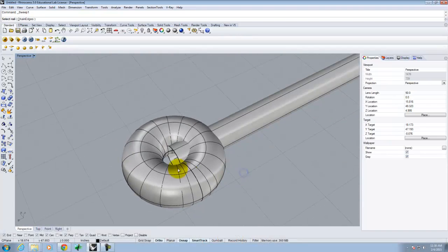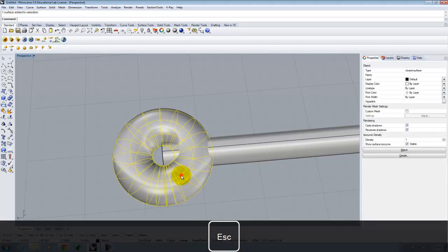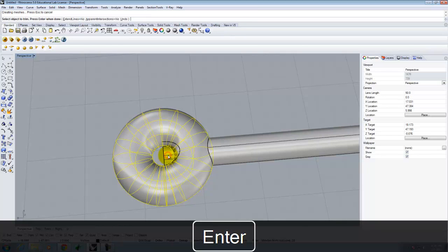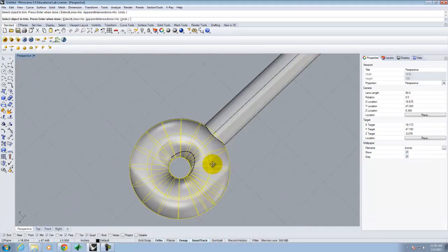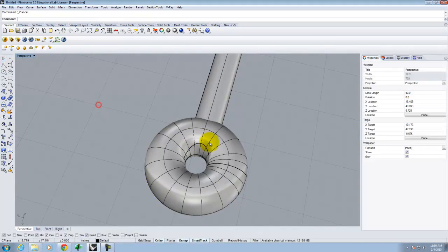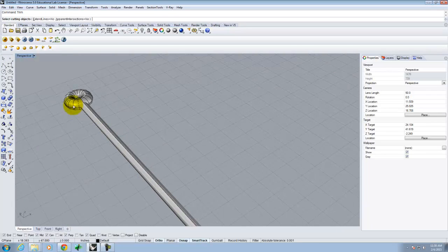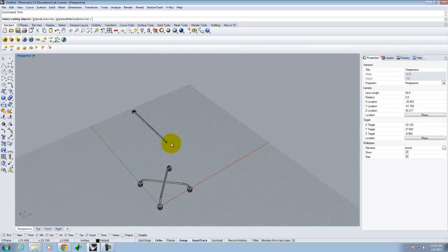Okay. Need to do a little bit more cleanup in that I need to make some trims. So let me use this object here, and I'll type trim, and I'm going to trim off those 2 pieces of the object. Okay. And I end up with a very nice little donut, right? My rod, etc. Okay, so now I need to rotate this up in 3 dimensions so that I can put it right here on the little clamp.